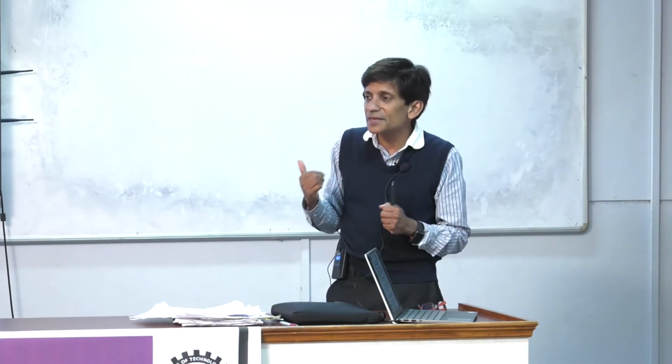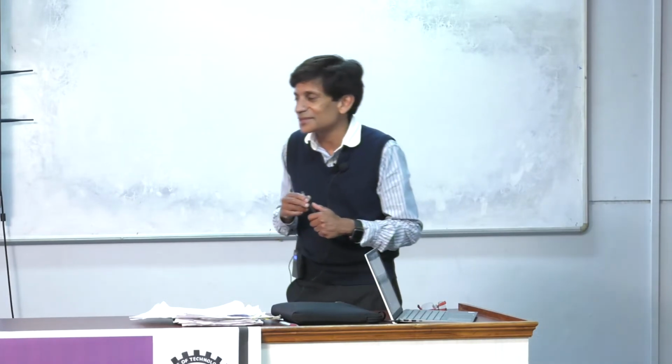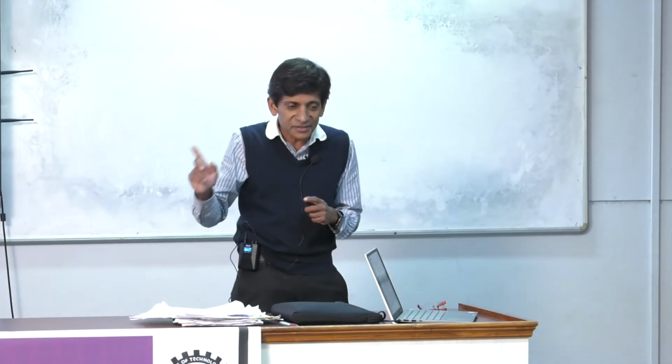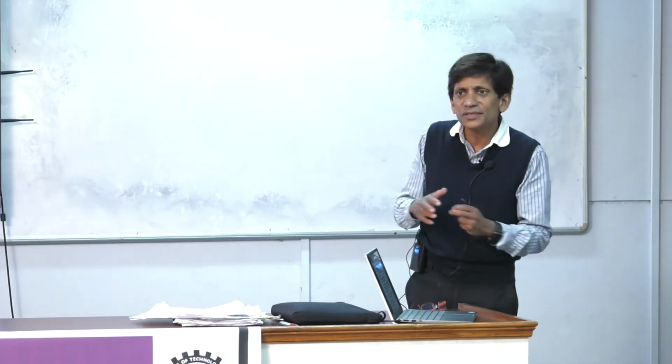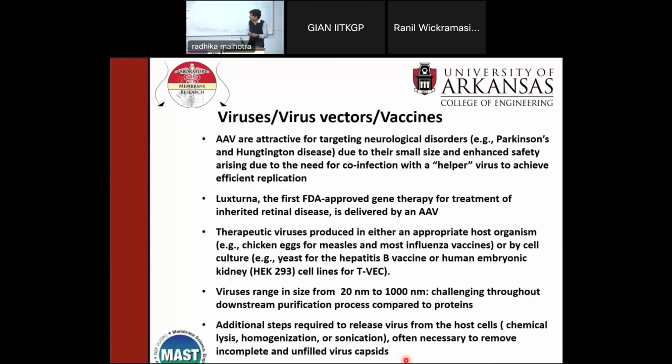Most viruses, in fact, I don't know an exception to this, but there probably is, so I won't say that more. But most viruses, the virus particles, the majority of them are inside the cells, okay? A few are excreted through, but the majority are inside the cells. So for this to be an efficient process, you're going to have to lyse these cells. And lysing, whether you do it by chemical lysis, you can use a chemical way to rupture the cell membrane or make it more porous, or if you use homogenization and sonication, you smash up the cells. Whatever you do, it's going to be complicated because now you have all this cell debris floating around.